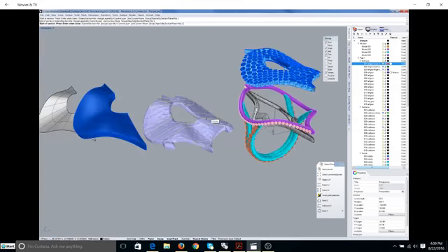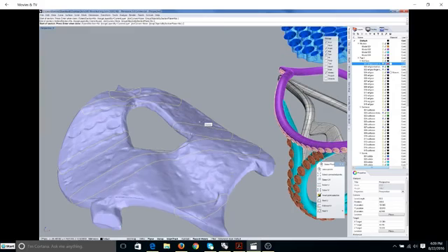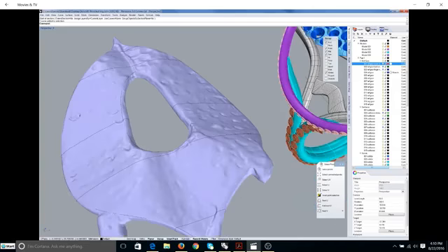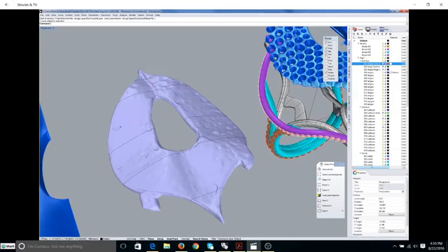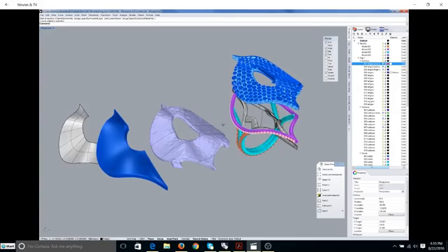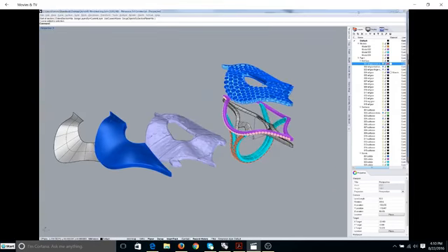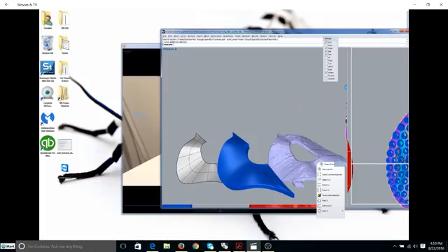So obviously, these cross sections are polylines. Remember that we're projecting onto a mesh surface, so these are degree 1 curves with just a very large amount of points on them. At this point, this would be turned into a degree 3 curve, which you can then use to effectively rebuild something. Great way to get cross sections. So that's one example. Now let's go into another. Let me move this over, and we'll take another example for you.